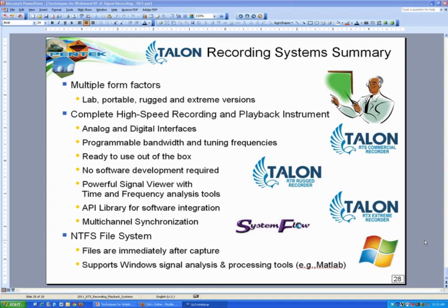One more question. Can you provide higher sample rates like 3.2 gigasamples, 12 bits like your SDR? Yes, as a matter of fact, the A to D converter that we're using for the digitizer that I claimed 8 bits in is actually a 3.6 gigahertz 12 bits, and the only reason that we're limiting the capture to 8 bits is because of the current limitation of the storage rate that we have, which is 3.2 gigabytes per second.